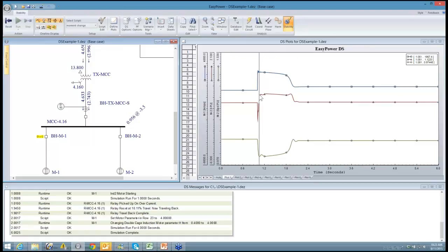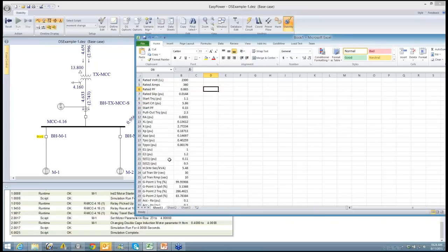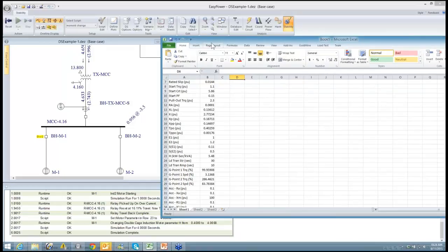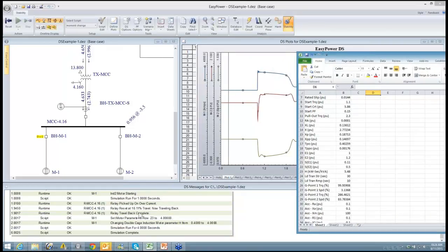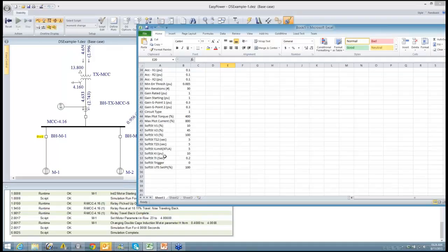Now, the reason for going to all this trouble to show you how to change this is that it works with any of the parameters in the characterization of the motor itself. So we've effectively been changing the moment of inertia, which by default started at 0.4, and we've changed it to 4.0, which is the step right here. And so you can pick any of these parameters and vary it as your heart desires to see what's going to be the effect in the system.